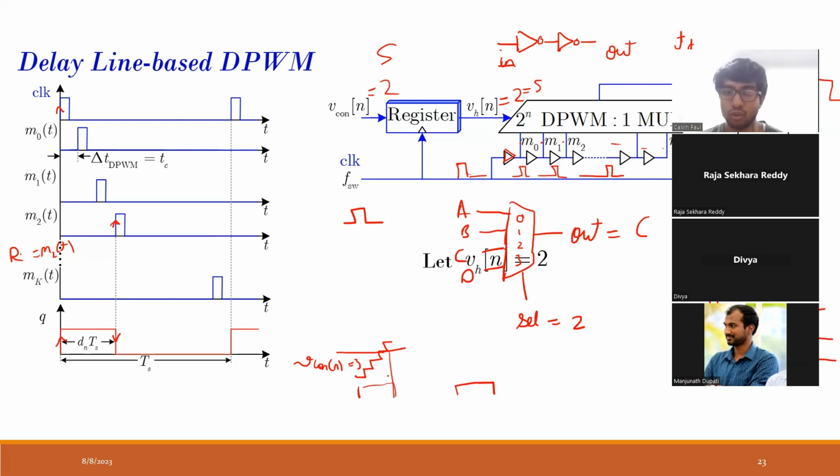Like that. So my clock over here is just one clock. The frequency of this clock is not high, but the clock is being delayed progressively, and then I am choosing the desired delayed signal to generate the desired duty ratio. So this is the advantage. I do not require a high frequency clock, but I'm using a certain number of delays, and I can get the resolution which I want without having to use a high frequency clock.